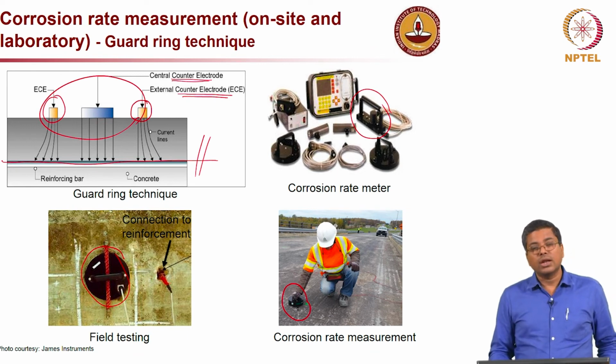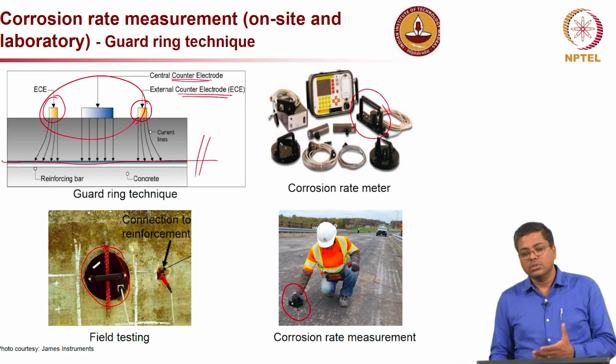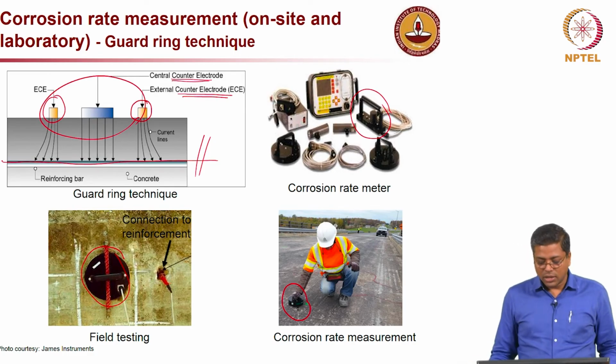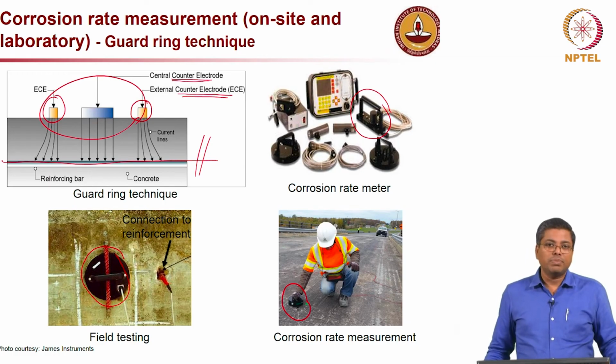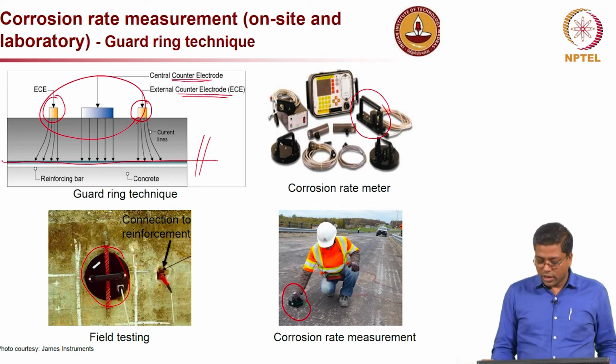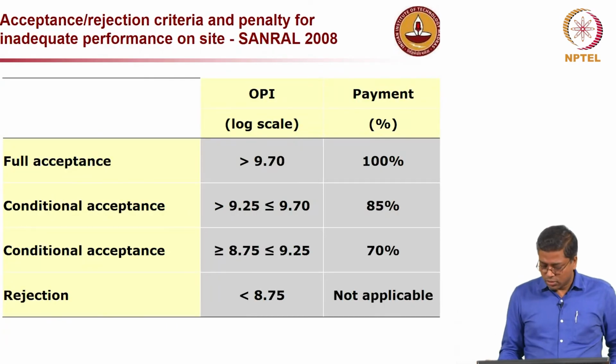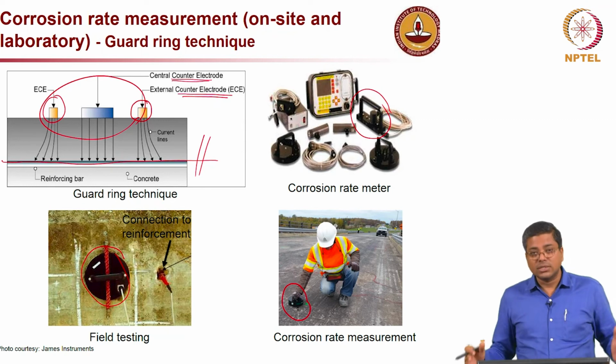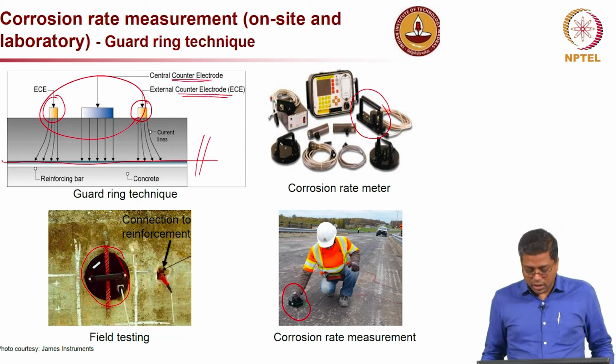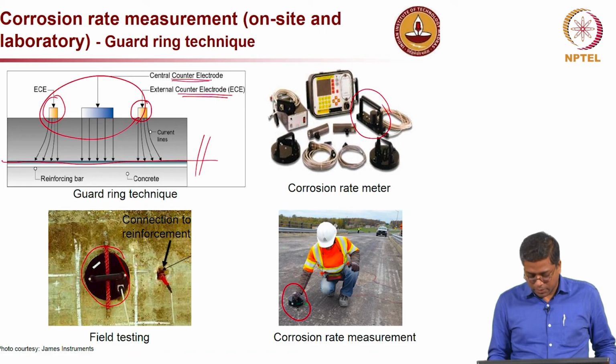Once you know the rate of corrosion, either by assuming a linear or uniform constant corrosion rate for the wet period and some other rate for the dry period, you can determine how long it will take for the reinforcement to lose a certain amount of cross section. That will help in budgeting money for that particular repair work if necessary.